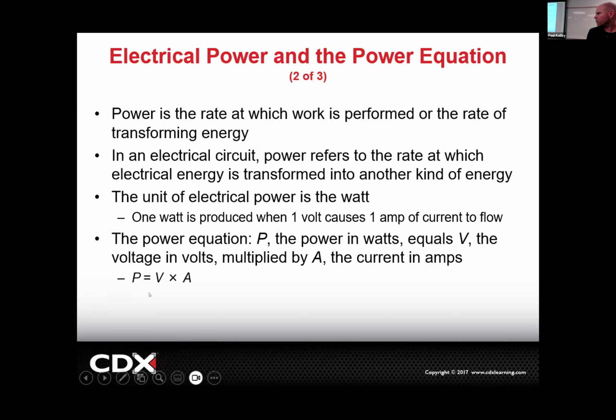But if you were to have 24 volts, you'd only need a half an amp to make 12 watts. So you could actually lower the amps, which means you could run smaller wire, which means you could save weight and probably money on conductor sizes and space and everything. So don't be surprised. They already started doing this. A Tesla EV now runs like a 16 or 18 volt lithium battery. They don't have a 12 volt battery anymore. And that's probably some of the reason.